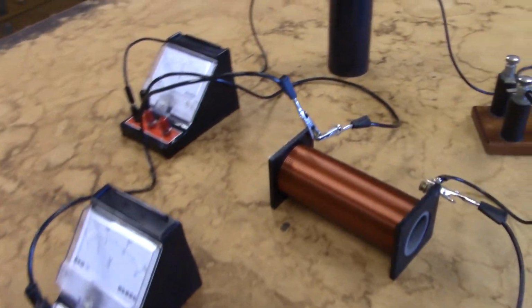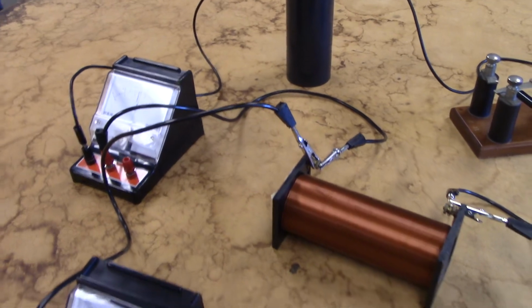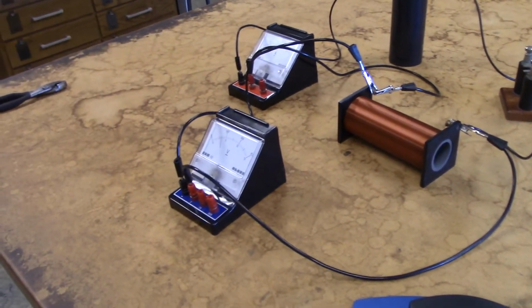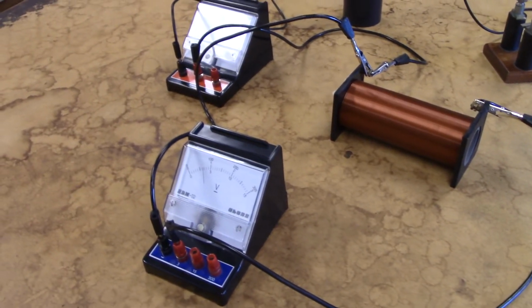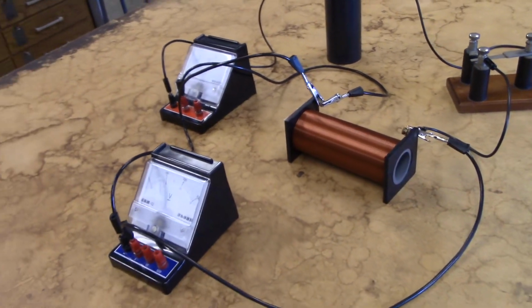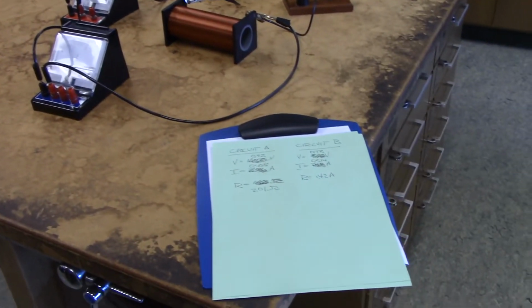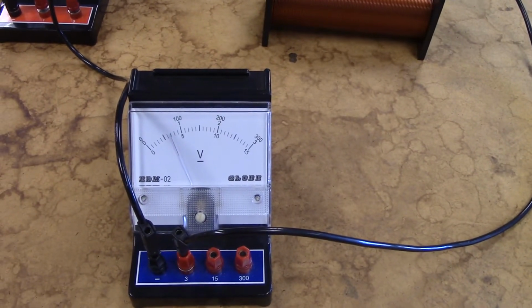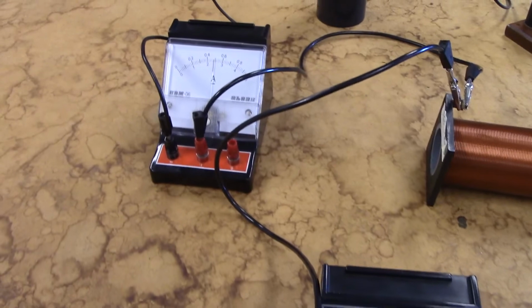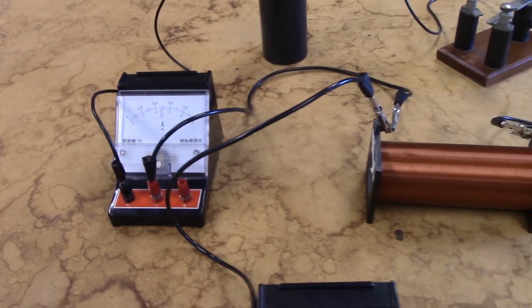So we've probably got some resistance, not just in the ammeter, but also in the wires. And these aren't really super precision voltmeters and ammeters, so in some ways it's a good measure of what we talked about. The voltage did drop quite a bit, and then the current went up some. The current now went up to 0.514 is what I was measuring.